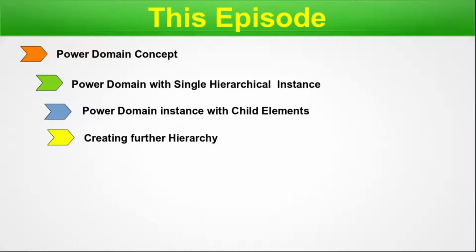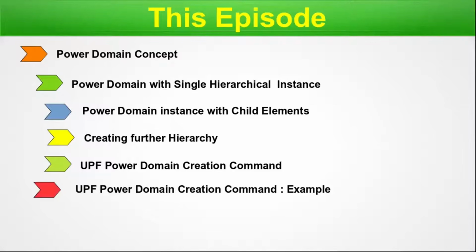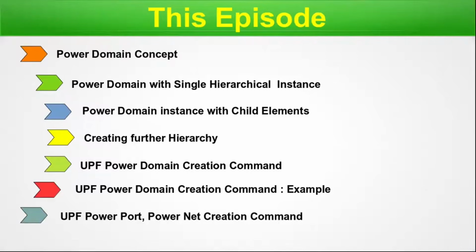We'll go down further by creating more hierarchy. Then we will explore the UPF power domain creation command. Next, we'll go through a detailed example of the UPF power domain creation command. Finally, we'll discuss UPF power port and power net creation commands.